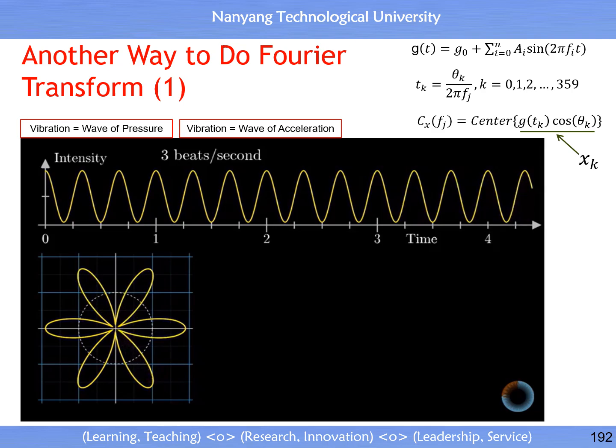And right now, I'm drawing it in such a way that moving forward 2 seconds in time corresponds to a single rotation around the circle. Our little vector drawing this wound-up graph is rotating at half a cycle per second. So this is important. There are 2 different frequencies at play here. There's the frequency of our signal, which goes up and down 3 times per second, and then, separately, there's the frequency with which we're wrapping the graph around the circle, which at the moment is half of a rotation per second. But we can adjust that second frequency however we want.